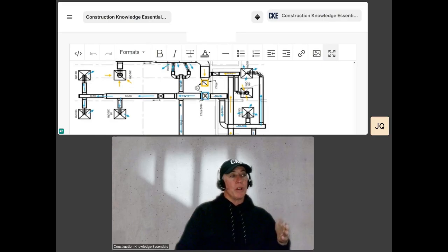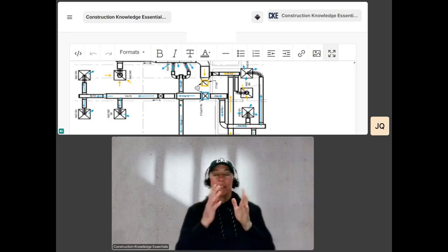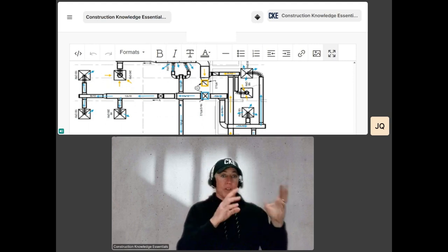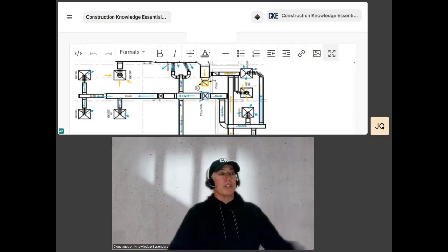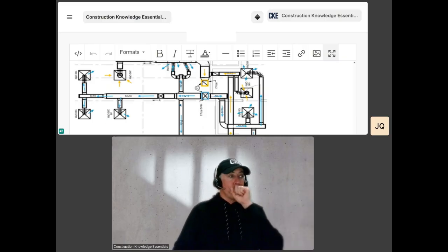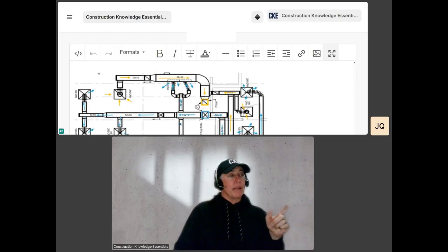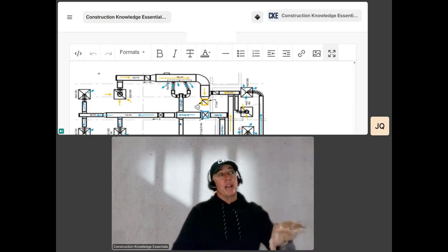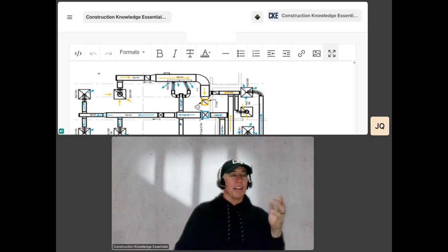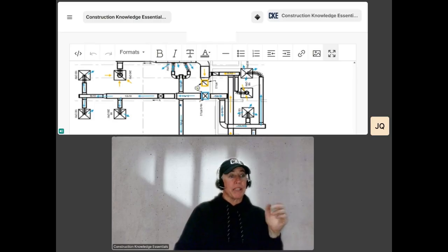So this is your unit right here, blowing air, blows this way, and each of those trunks gets smaller to keep the CFMs or pressure at a certain amount, so it stays pressurized throughout, so it's not just falling out of the unit at the very end. It's calculated in order to make sure that it's done properly like that. Same idea here. This is flowing out. It looks like it's part of the same unit because the return is running above the supply. So it has that visual as though that's what you're seeing, but it's not.